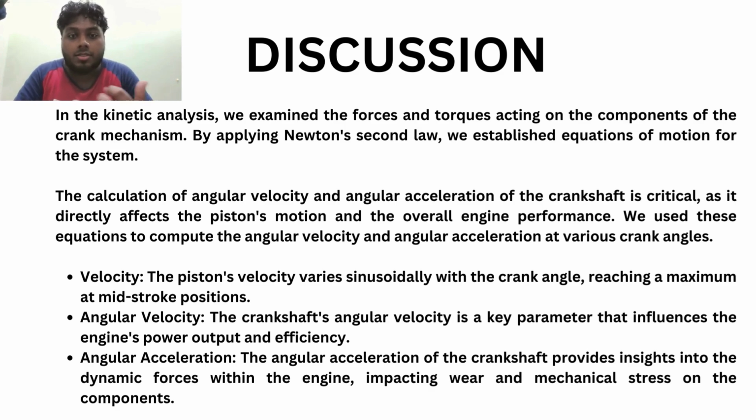For the velocity, the piston's velocity varies sinusoidally with the crank angle, reaching a maximum at the mid-stroke position. For the angular velocity, the crankshaft's angular velocity is the key parameter because it influences the engine's power output and efficiency. We calculated angular acceleration as well. The angular acceleration provides insights into the dynamic force, so we can see the impact of wear and mechanical stress on the components. With all this, we can build a more efficient engine with the application of dynamics.